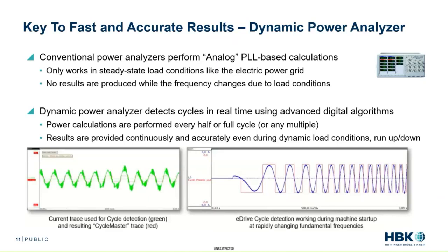And so what you see in the lightly red waveform there is a square wave. Basically, that's just showing you the zero crossing points on that waveform. And that's used as a basis for calculating the RMS. But on the right side, we also see a similar waveform here in blue that, for example, could be current, once again, from an inverter on one of the phases of current.